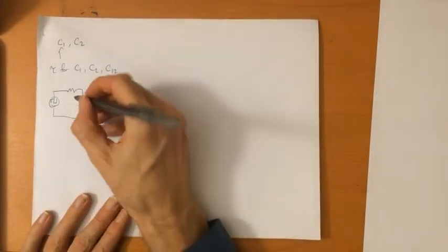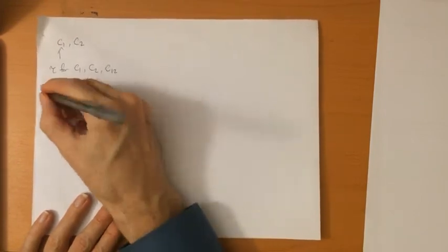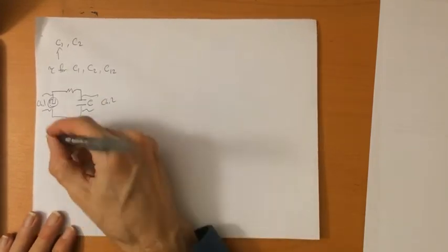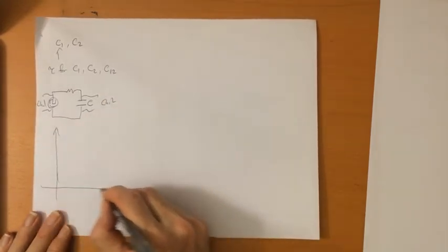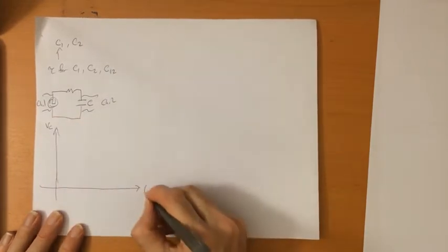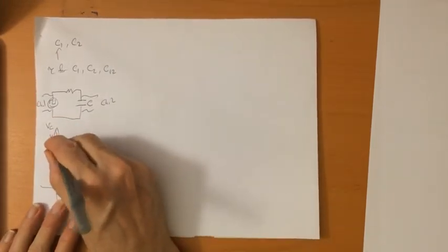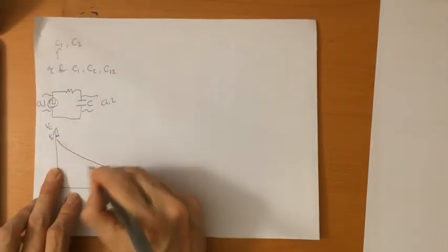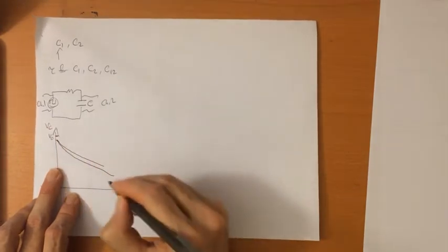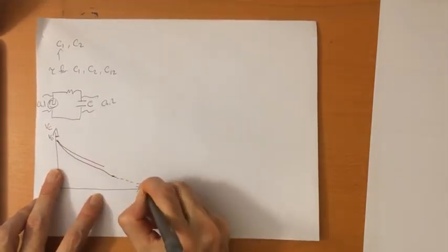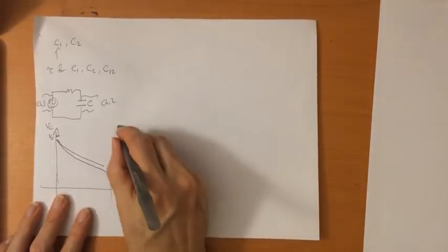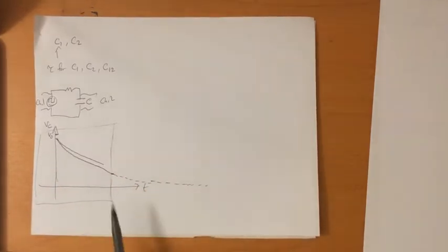But anyway, for part C we're going to use the same circuit with the same oscilloscope connections, but we're going to change the oscilloscope screen, so what you're going to see on the screen is going to look more like this. We're going to basically blow this thing up. You're going to have some initial voltage, and there's going to be a 0 line here. It's going to look something like this. Now, there's an implication that this thing will eventually decay to 0, but you won't see this on the screen. You'll just see this part of the screen here.